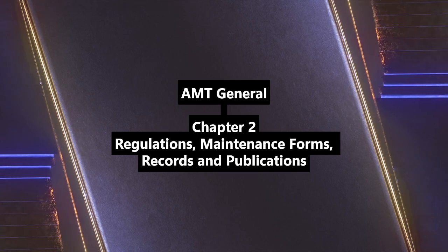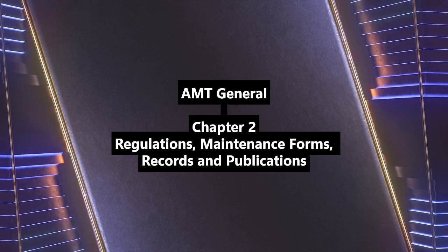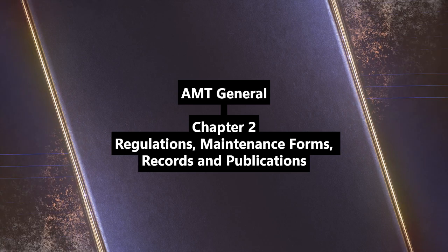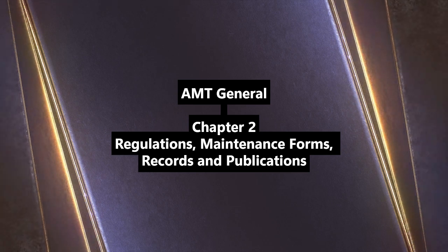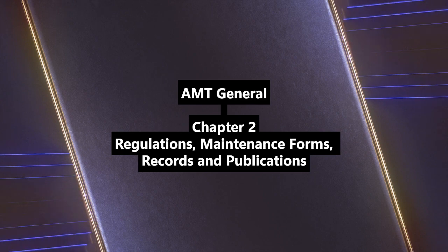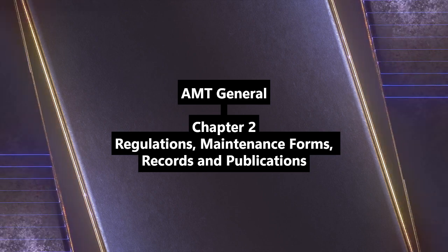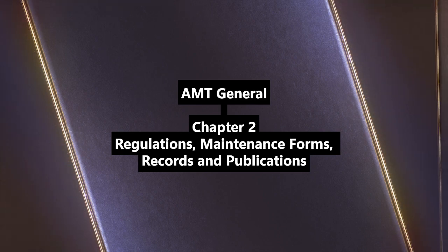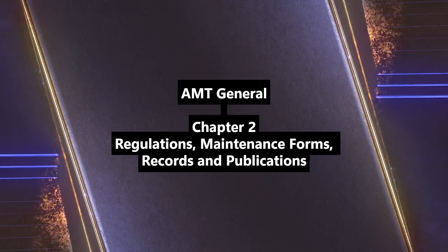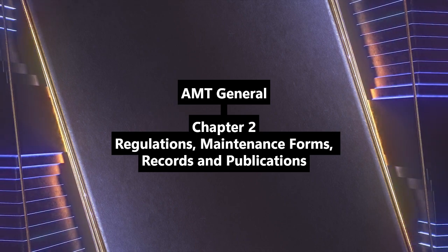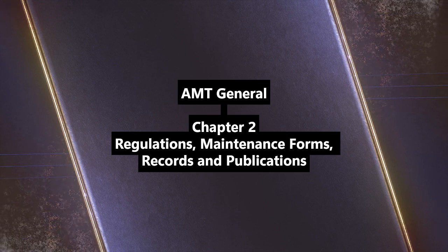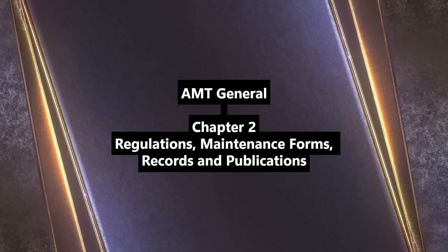That would be 14 CFR Part 43: maintenance, preventative maintenance, rebuilding, and alterations. The core maintenance rulebook. Absolutely. Its 13 rules and 6 appendices set the standards for maintaining basically all U.S. registered civilian aircraft. And it works hand in hand with Part 91 for continued airworthiness. Okay, Part 43. We'll definitely need to dig into that one more.